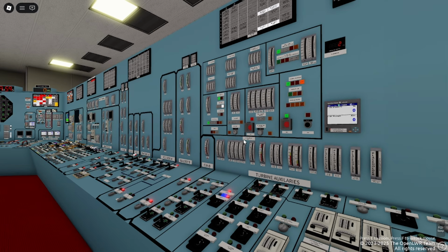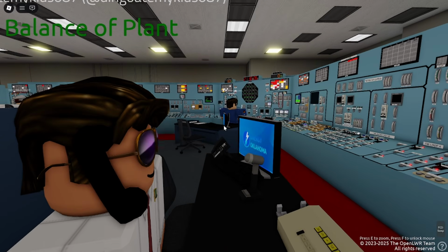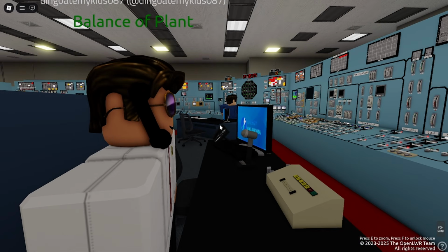Control room to party line 1. Equipment operator on party line 1. I would need you to reset DG2 lockout trip and run it up. So that will be a DG2 lockout reset and run up. That is correct. Okay, equipment operator understands and out.